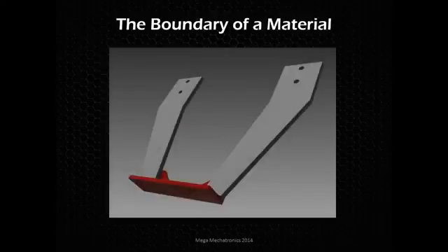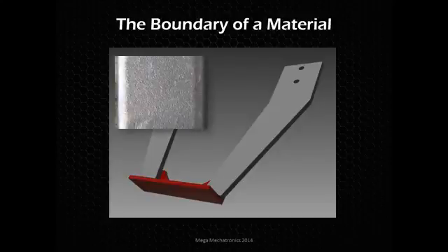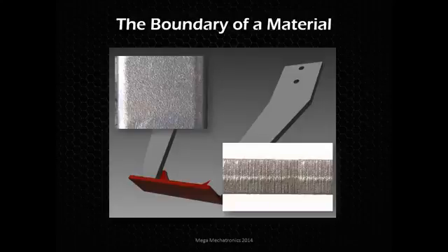So looking at a part like this, this is a CAD model obviously, you can imagine through the manufacturing processes that you are thinking of using when building the part, you could get an idea of the big surfaces being shot peened like this, where you would clean it up, and the edges, let's say you cut it out with a CNC plasma cutter, the edges would look something like this, or similar depending on the technology, if it was a laser cut or used a plasma jet style of a cutter.